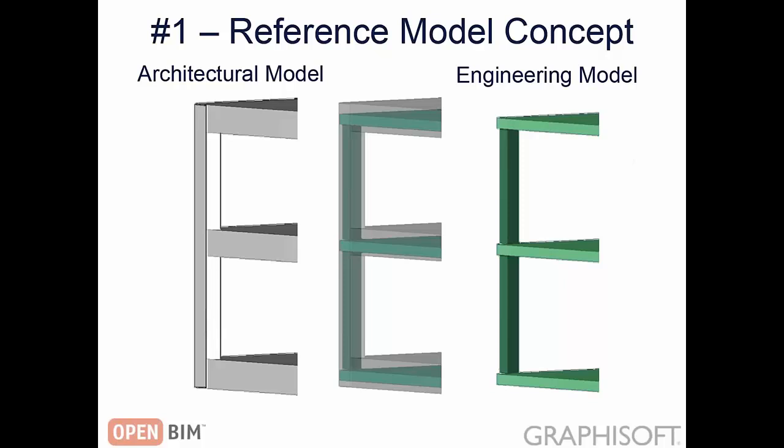And the reference model is something that sometimes confuses people, what we mean by that. This is just a very simple example: when we have the architectural model and an engineering model, on both sides, the other one is the reference model. So the architect can load the engineering model into the architectural model and compare, for example, the dimensions and locations of the different objects with his designs. And vice versa, the engineer can take the architect's model and compare that. But they are not necessarily exactly identical.